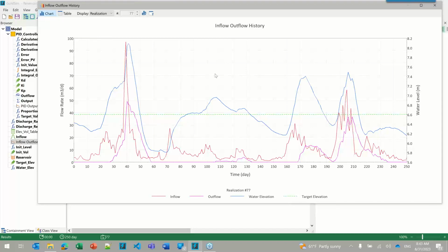And so this type of control logic is probably better for rapidly varying inflow rates with a smaller volume storage component. So like a tank, I would say, where this could be more applicable. And you can also tune the controller by adjusting those rate coefficients to get a better response.